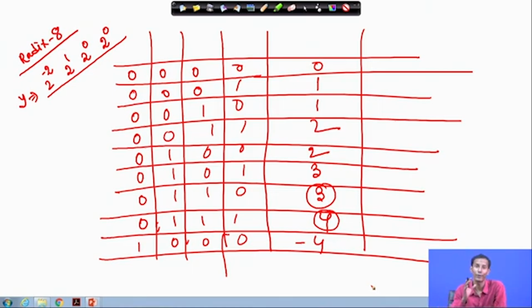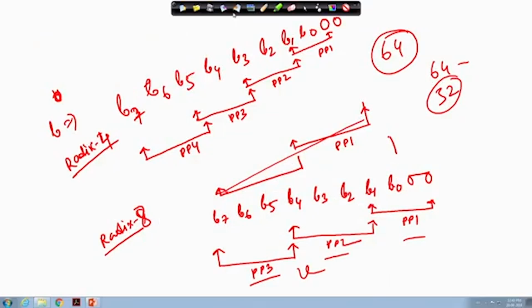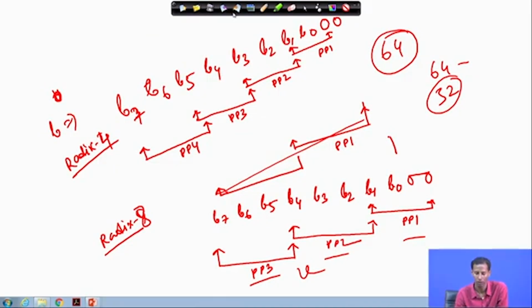Okay. So, we have to choose this number of radix in a judicious way, so that I am getting the benefit in terms of delay, that means stage reduction, whenever we are considering higher radix using this Booth's algorithm. Okay. So, that we have to be more cautious about. So, here initially I was needing 4 for this 8 bit operation, but here I need 3 stages.